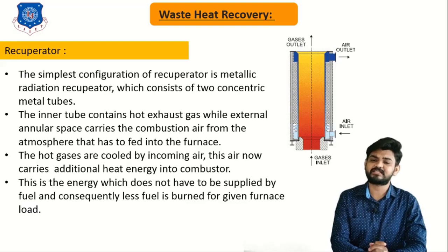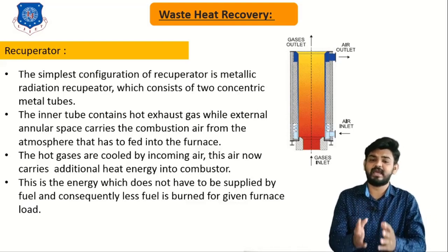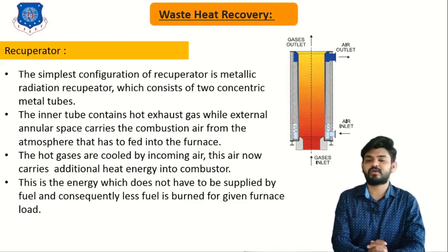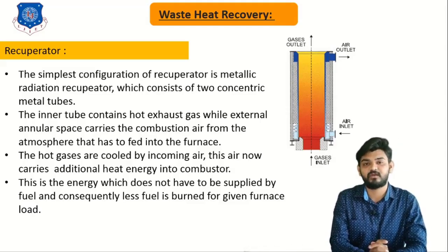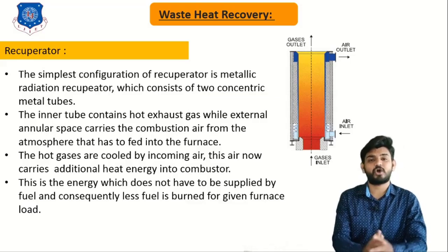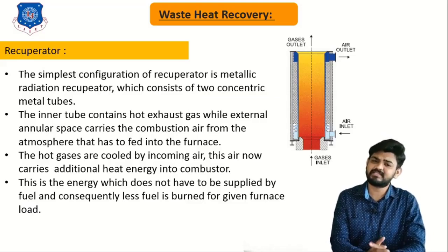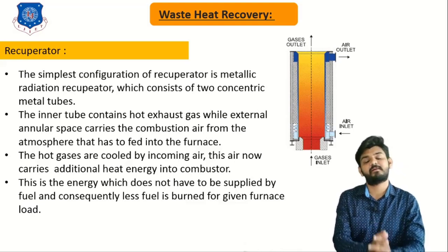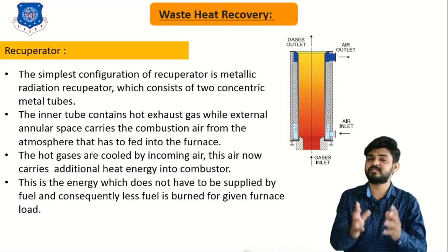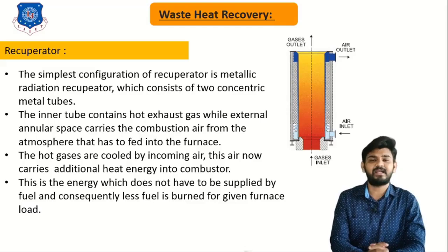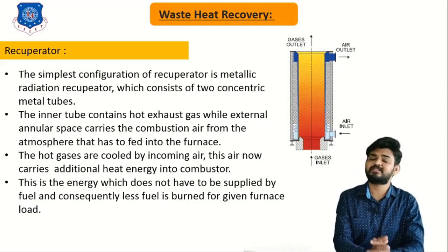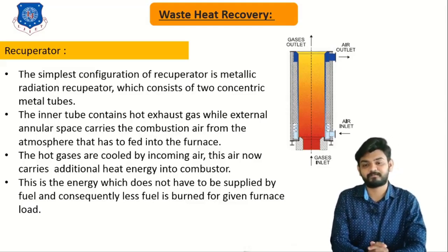The hot gases are cooled by incoming air, thus the air carries additional heat energy into the combustion. What happens is, the hot gases transfer their heat to the air, and this air is preheated by exchanging heat with the hot fluids, which ultimately reduces the energy required by the combustor.